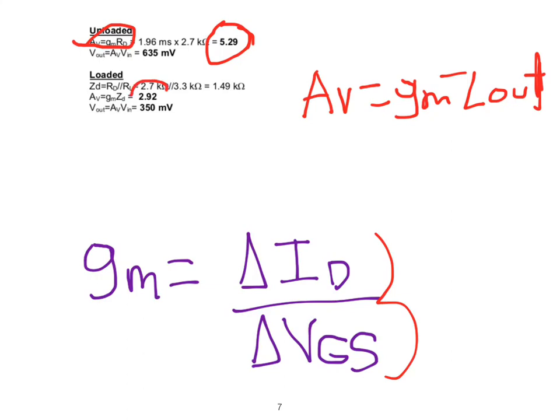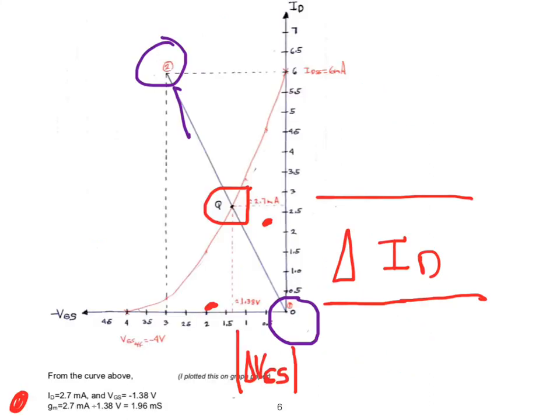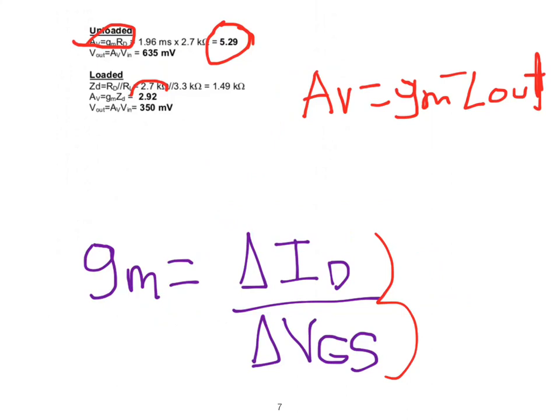Okay. So you notice that the CS amplifier has a very low gain, and that is simply because the curve here is incredibly non-linear, so you don't want the Q point moving around too much. So by biasing the Q point roughly in the center of the curve, and limiting its movement to an approximately straight line area of the curve, then the output is reasonably linear.